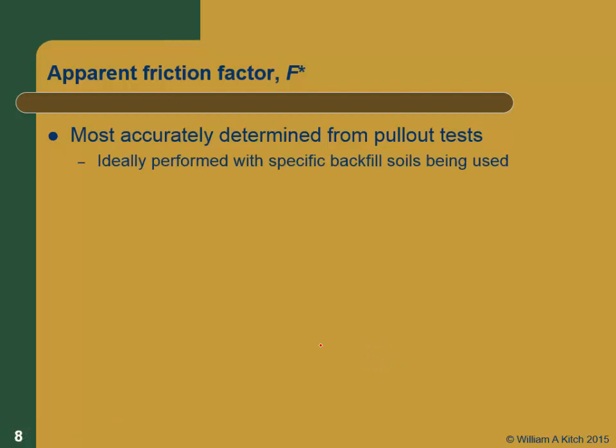I should point out that the material that you're going to reinforce is going to be dependent on what your site is, and if you don't have pull-out tests with that material, it would behoove you to get tests with that material. If you have pull-out tests from a manufacturer and it's from a material you think is close enough to stuff that you're going to use in the backfill, and you've got a fairly low-risk wall, and you just want to use their numbers, that's fine.